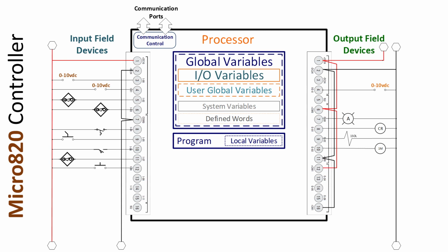So what you download into the RAM is subject to control by the executive software or the firmware. But let's stay away from that. Let's just talk about the RAM, the part that's volatile in a sense, the part that you download to. And primarily you have two sections mapped out, global variables and programs. We divided it up into two boxes.